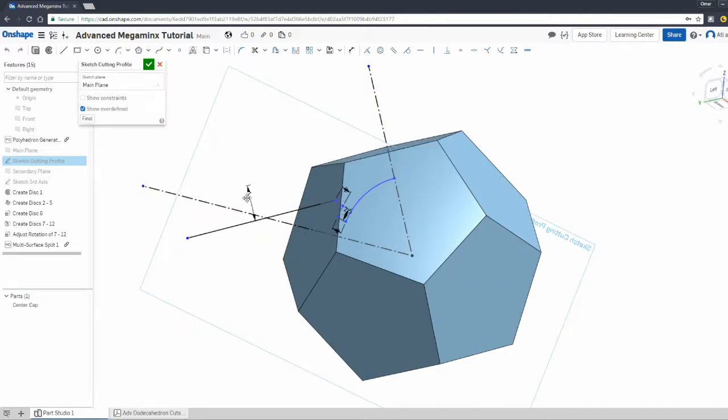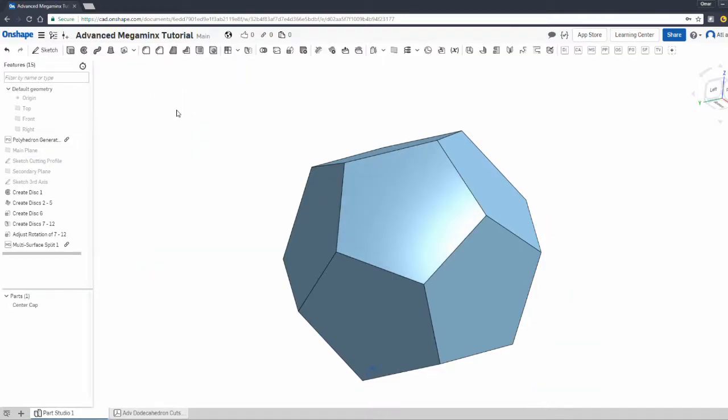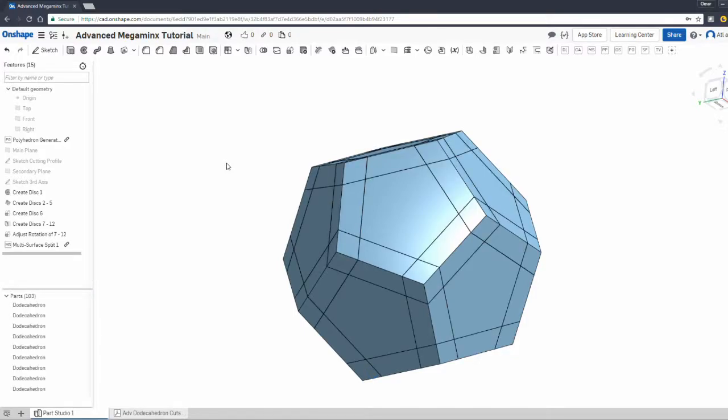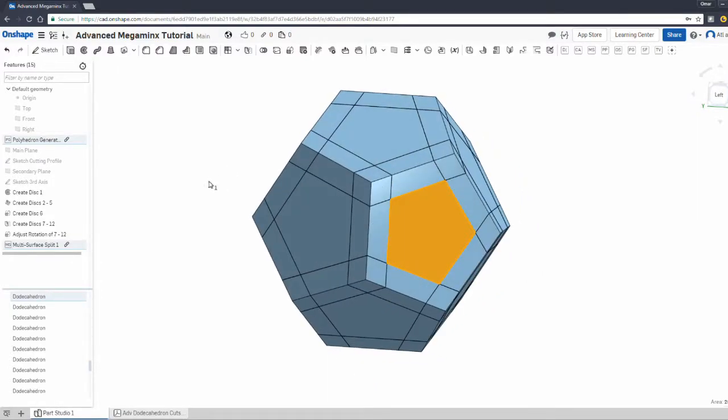And just to show you really quick, if I reduce the distance, say to 4 millimeters, and click OK, I'll still get a Megaminx, and it's still going to work, and you can 3D print it, and it's fine. But you'll notice that my centers become huge, the pentagons are pretty large, the corners are tinier.